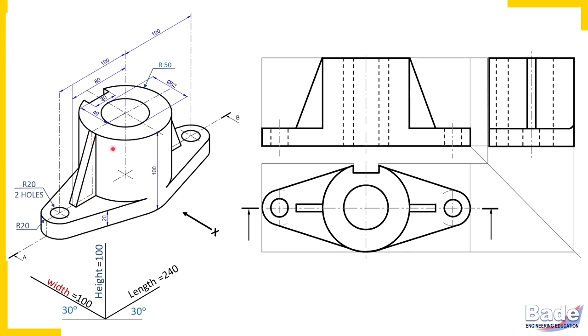Such plates connecting major parts of an object or major portions of a machine part are called ribs. So this triangular plate is a rib. Ribs are thin plates which connect major portions of machine parts to increase the strength of machine parts. Such thin plates or ribs, we never consider getting cut by a cutting plane. We assume these ribs intact.